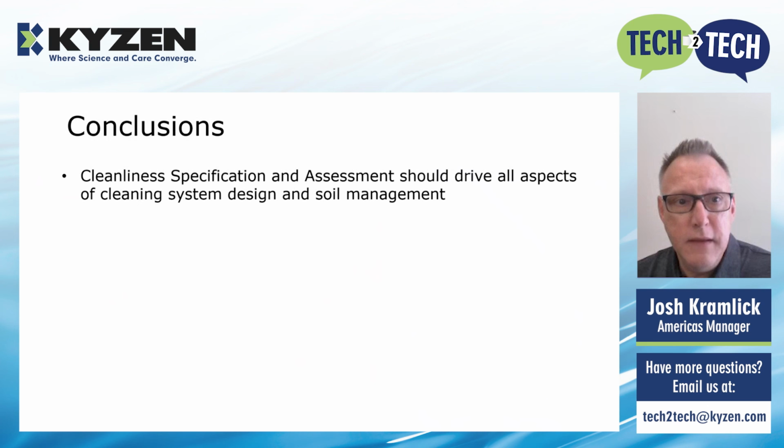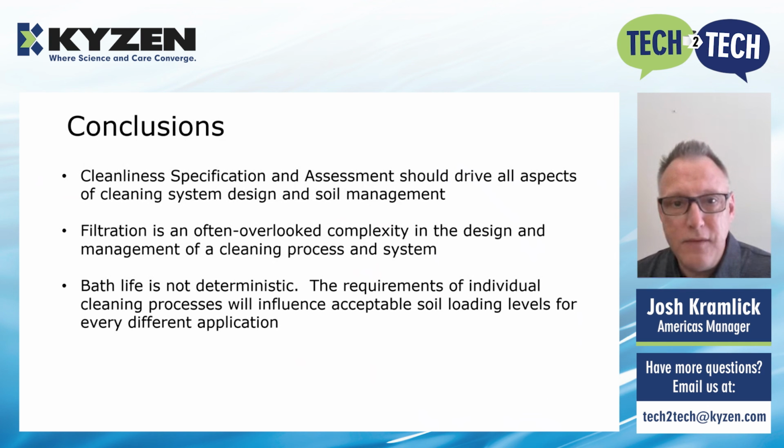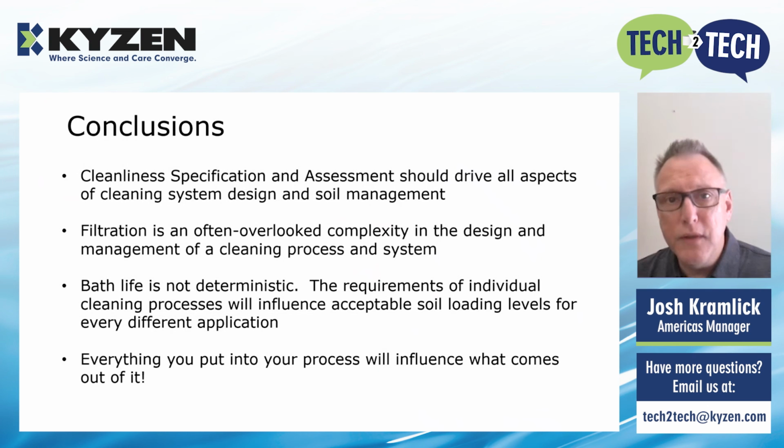So in conclusion, cleanliness specification and assessment should really drive all aspects of the cleaning system design and the incorporated soil management. Filtration is often an overlooked complexity in the design and management of a cleaning process and system. Bath life is not deterministic. The requirements of individual cleaning processes will influence acceptable soil loading levels for every different application. And most importantly, everything you put into your process will influence what comes out of it.